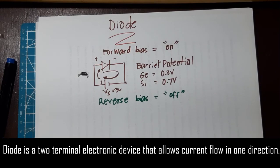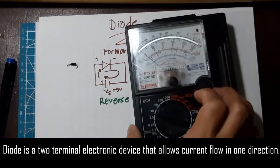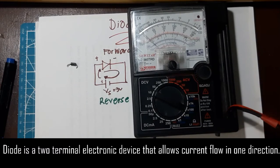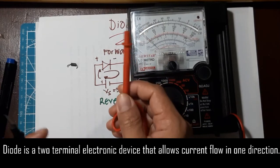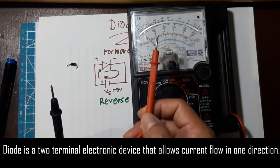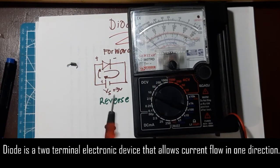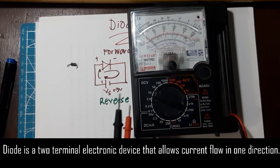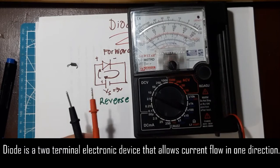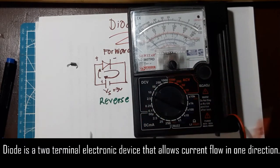Okay, now to test your diode, you have to use your multimeter. By the way, my red test probe is considered to be negative, and my black test probe is considered to be positive. That's not always the case in other brands. It just so happened that my tester here is somehow using conventional current flow.